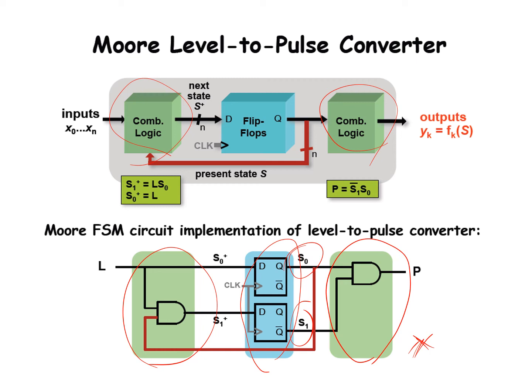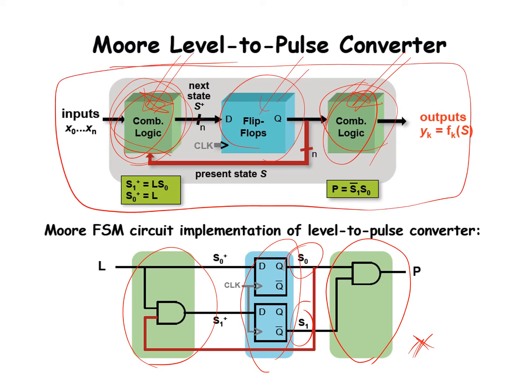So in Verilog, what you have to do is describe this combination logic here, describe the combination logic for the output, and define the flip-flops like this. So you have to remember this structure itself to describe it in Verilog. You must understand this kind of structure, right? Without knowing such concepts, you cannot properly write the Verilog code.